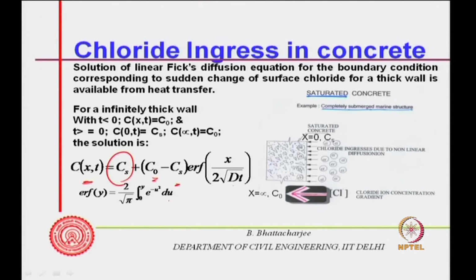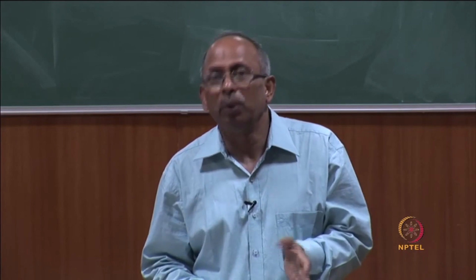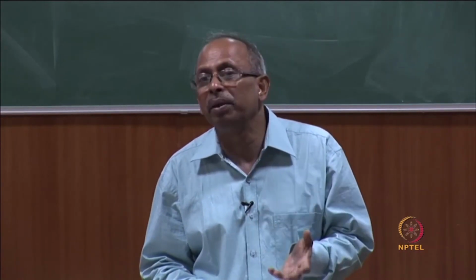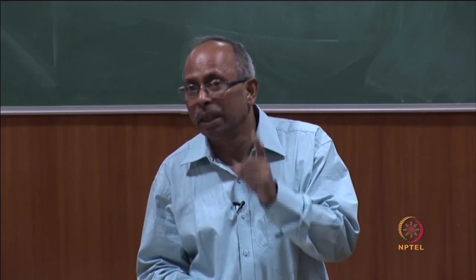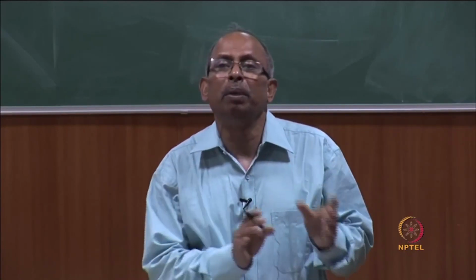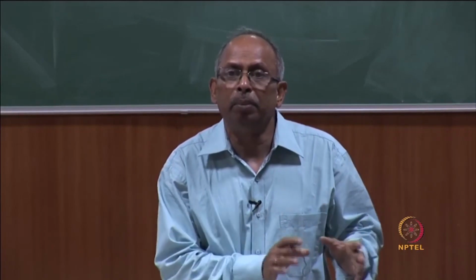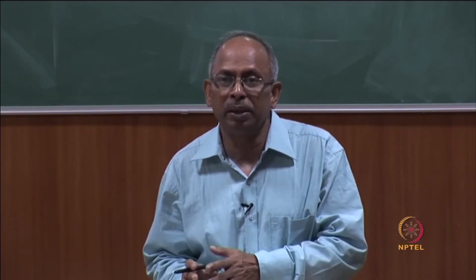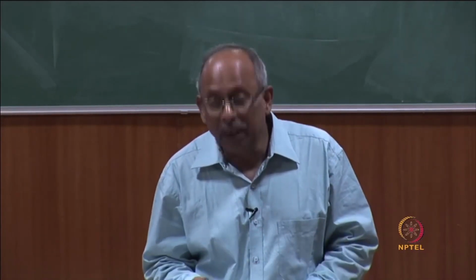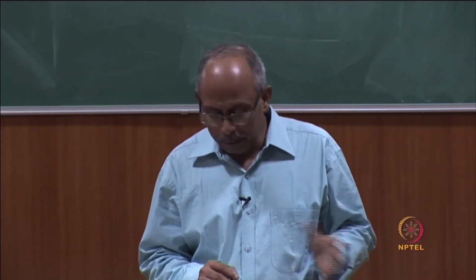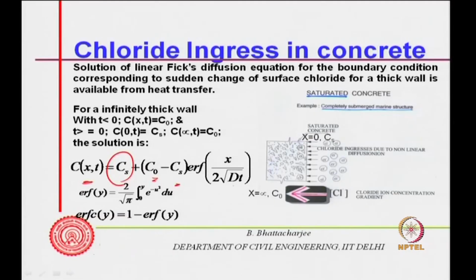So, this is a known solution, but this is not valid for all situations, although apparently a lot of people use this for all kinds of situations. It is only valid for a saturated chloride condition, that means possibly no splash zone, submerged concrete, where the concentration outside is constant, tranquil water, no change in concentration, and this boundary condition is followed. It cannot be used everywhere, but that is what has been done quite often.